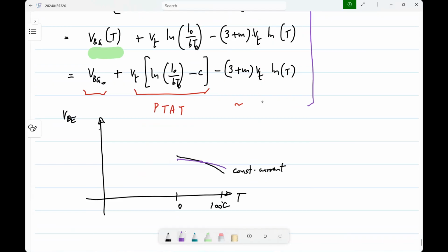But anyway, because we are using the PTAT cell, we can assume that the currents through our bipolar transistor junctions will be PTAT. This is something just to know. But still, everything else remains the same. We have a proportional to absolute temperature term which dominates, and we have a nonlinear term that we ignore.